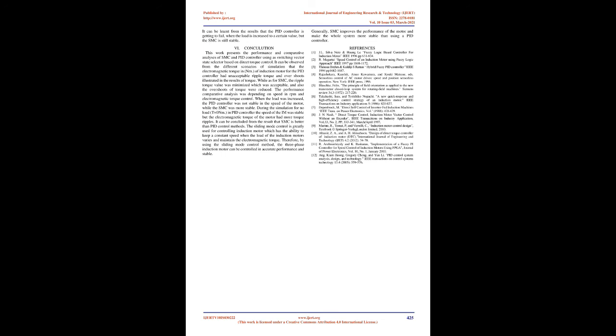The sliding mode control is widely used for controlling induction motors, having the ability to keep a constant speed when the load of the induction motor varies and to maintain the electromagnetic torque. Therefore, by using the sliding mode control method, the three-phase induction motor can be controlled with accurate performance and stability. Generally, SMC improves the performance of the motor and makes the whole system more stable than using a PID controller.